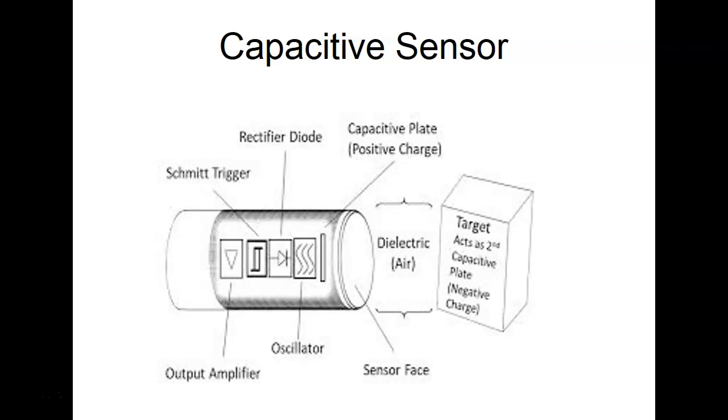Now you took AUT 208. So the ones that were sensing the blocks when they were in position, that was a capacitive sensor. But I could touch it with my finger, so I could trigger it with my finger, because I would change the dielectric when I came into contact with it. So these guys can sense about anything.